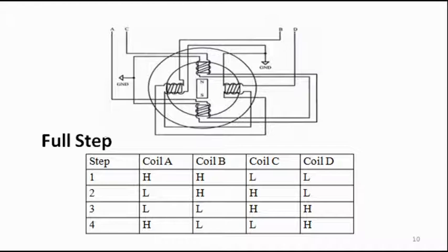So I have to add this step.c into my project. Under source group, add existing group. Next, search for the step.c, that is the stepper motor rotation. So I'll build it, and it is going to create the hex file.